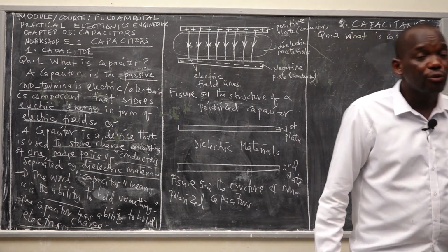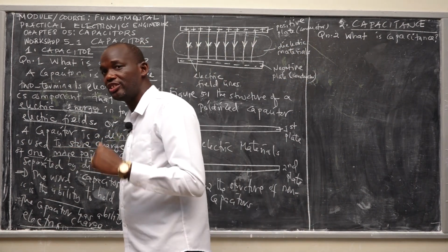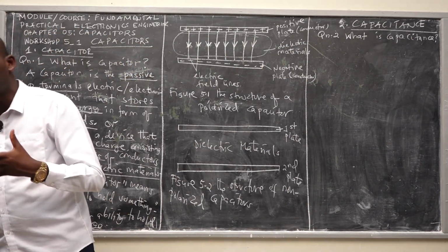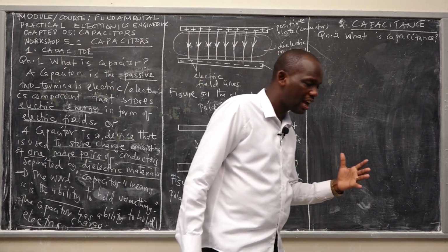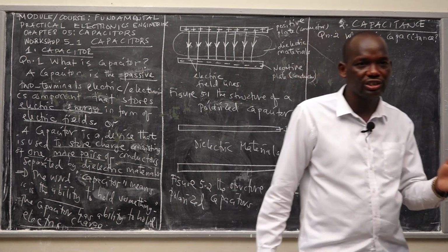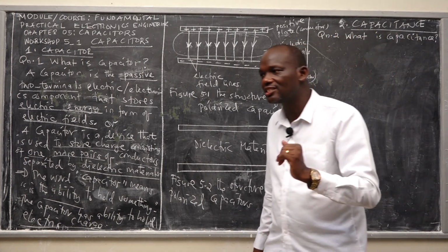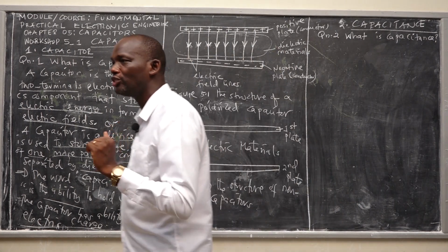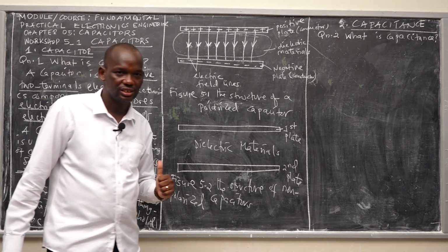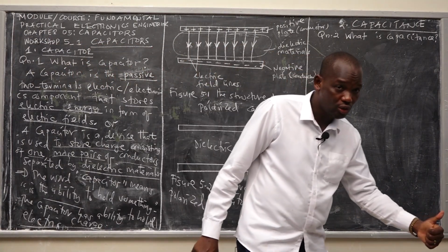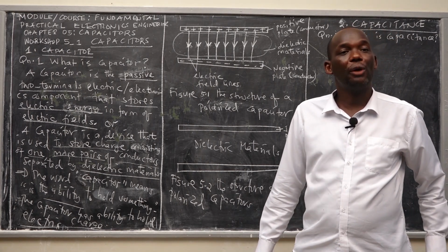Are we together? For instance, you might find that we have sensors called pH sensors. A pH sensor detects the pH of a solution, because you know that pH is the degree of what? Acidity or alkalinity, right? So you might find that sensor uses the property of either resistance, capacitance, or inductance to measure the pH of particular solutions or liquids.